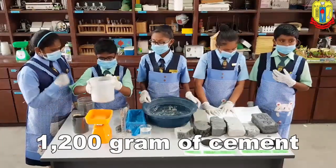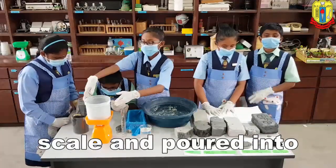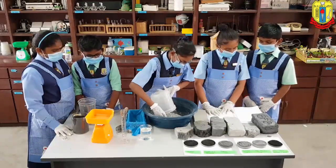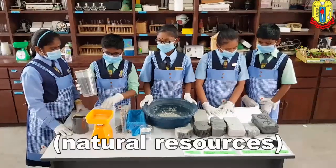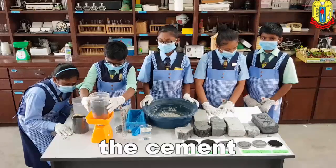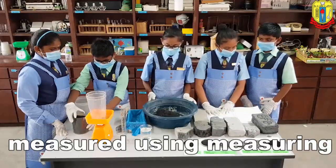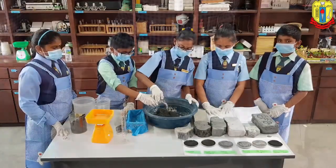Preparation methods: 1200 grams of cement was measured using a kitchen scale and poured into a plastic basin. 700 grams of bamboo ash was measured using a kitchen scale and added into the cement. 250 ml of water was measured using a measuring cylinder and poured into the mixture.